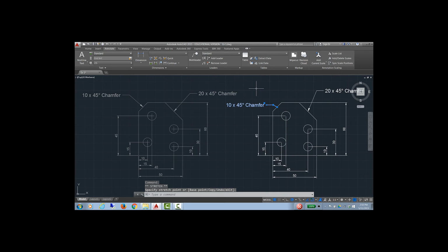Okay, so last but not least, the arrow's gone. That's interesting. Anyway, is to put in these center marks. So looking around up here, I couldn't find them anywhere, which was a bit annoying. So I clicked in here and just started typing center, and lo and behold, AutoCAD has searched through its dictionary and found there's some options. So dim center is actually the one we're after.